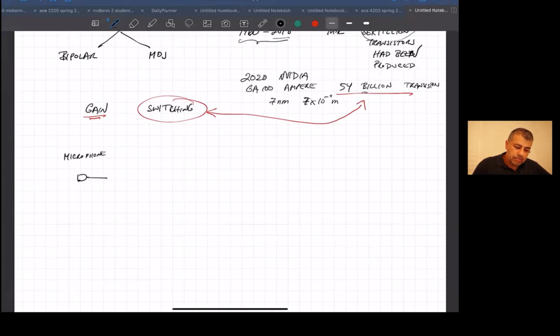And that might be pumping out, I don't know, hundreds of microvolts, maybe millivolts at its output, straight out of the microphone. So the first thing you usually do is gain that up to get above the noise. Then, I think we talked about this in the first lecture, the microphone's output frequency is in the kilohertz range. That's the human voice frequency range.